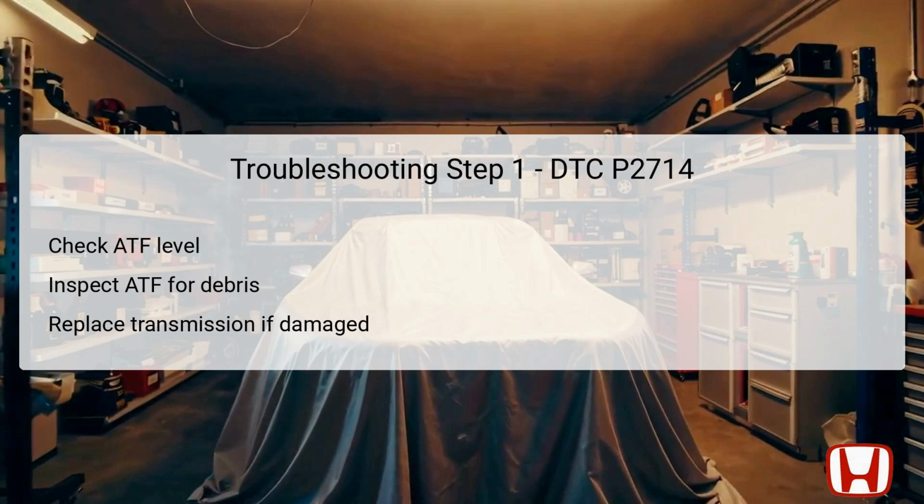Begin by warming up the engine to its normal operating temperature, ensuring that the radiator fan operates, which signifies proper temperature levels. Once warmed, check that the transmission is filled at the correct level and carefully inspect for any fluid leaks. Next, drain the ATF through a strainer and examine it for metal particles or excessive clutch material, as these indicators can signify internal transmission damage.